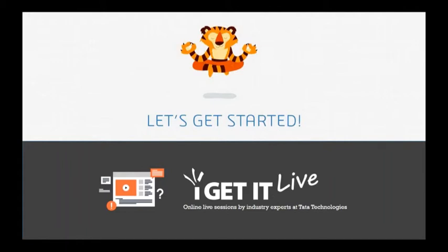So the environment that's created by default is for anybody that's logged into this machine, the settings that you change, the CAT settings document, for each individual login. So if you have 3 shifts, you have 3 logins, they can all be different. Okay, so we'll see how to manage that. Now, these used to be called secret environment variables because Dassault didn't really want you to use them. Well, they're all over the web now, so it's not difficult to find these.